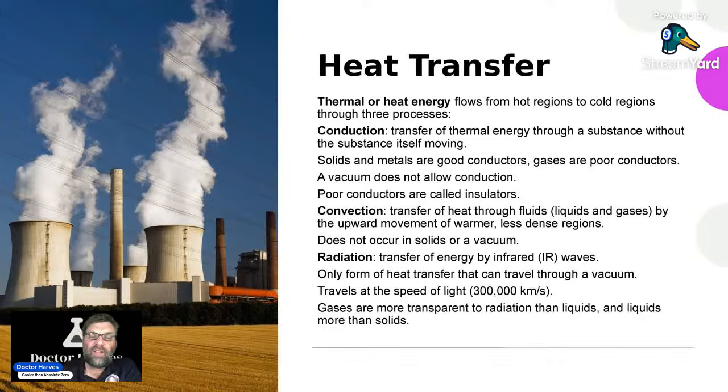Then we have radiation. It's a transfer of energy by infrared radiation waves. And it's the only one that can transfer through a vacuum, because it's basically electromagnetic radiation, so it doesn't need particles to transfer that energy. It travels pretty fast at the speed of light, 3 times 10 to the 8 meters per second. And gases are more transparent to radiation than liquids, and those are more transparent than solids, because there's lots of gaps between gases.